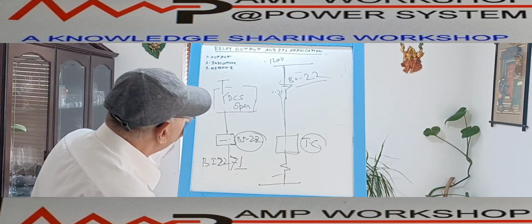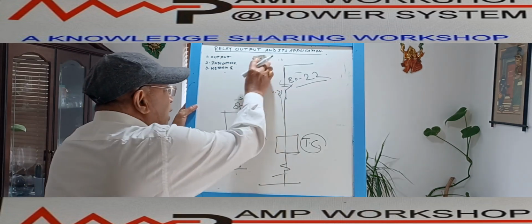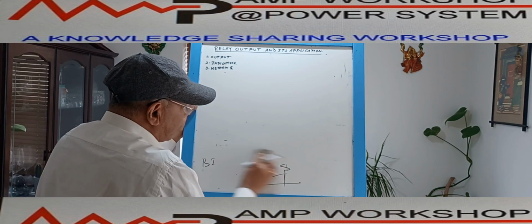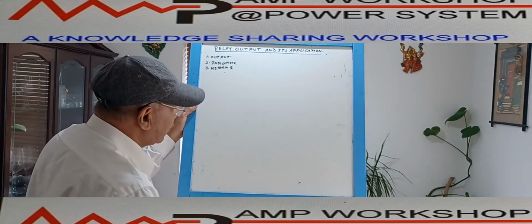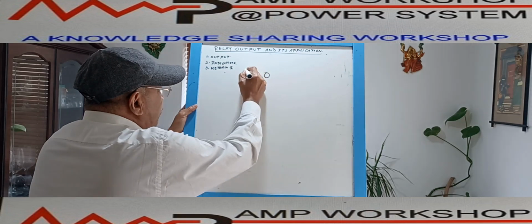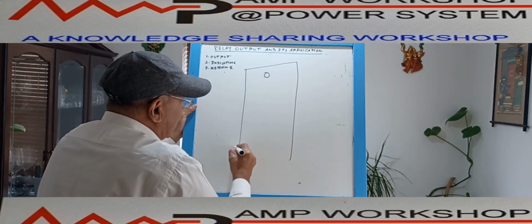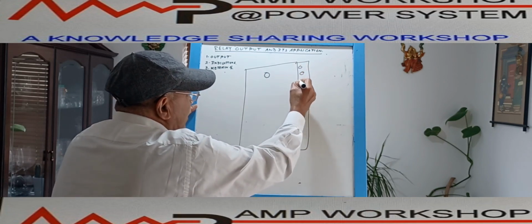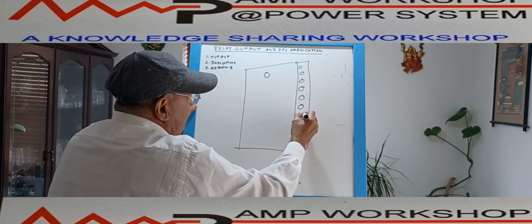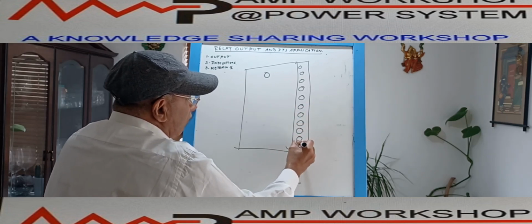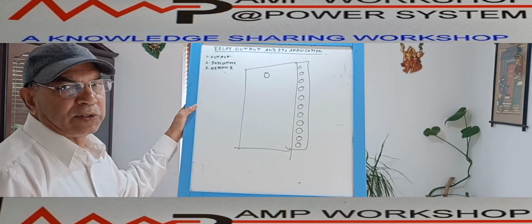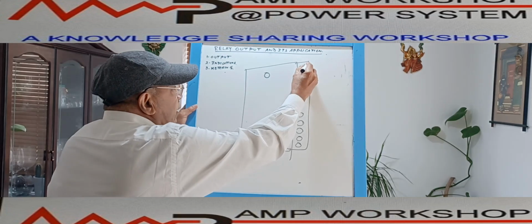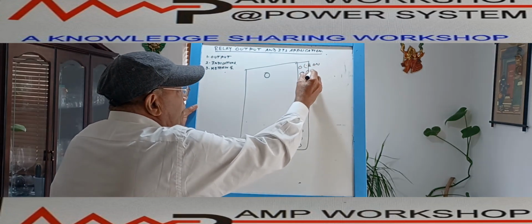In addition to this, we have said that the protection relay has multiple indication lamps. Suppose there are 16 indication lamps. Suppose this is the relay; on the side of the relay you can see a lot of indication lamps. These indication lamps we can configure for various purposes. Suppose this is CB ON, you want to configure CB OFF.